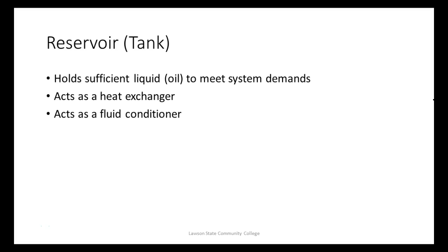Reservoir holds sufficient liquids to meet the system demand. So what you're supposed to do is have a level in there so you can keep the pump from cavitating with all your actuators fully extended. And that's what you're supposed to put.